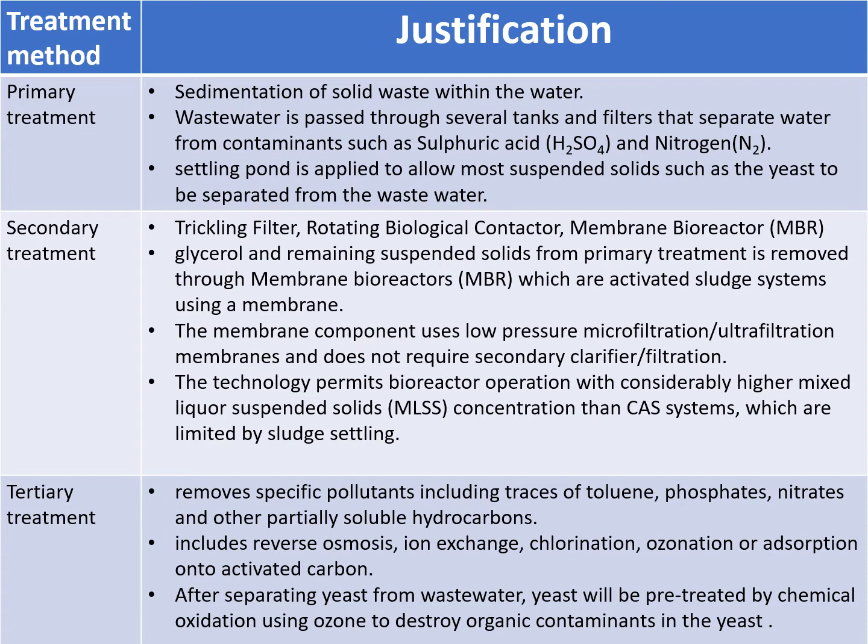The membrane component uses low pressure microfiltration or ultrafiltration membranes and does not require a secondary clarifier. The technology permits bioreactor operations with considerably higher mixed liquor suspended solids concentration than the conventional activated sludge system, which are limited by sludge settling.